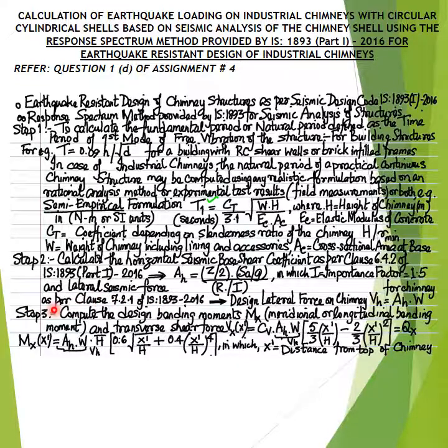In step 3, we compute the design bending moments, which are the longitudinal or meridional bending moments in the terminology of the theory of cylindrical shells, denoted as M subscript X in the context of earthquake loading or seismic effects on chimney structures, as well as the transverse shear forces denoted as V subscript X related to the design bending moments, that is the longitudinal or meridional bending moments Mx, using the formulations provided